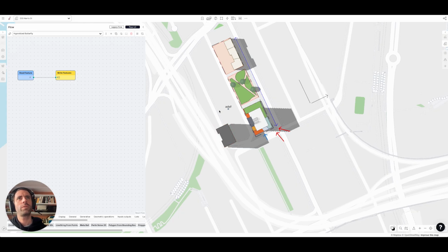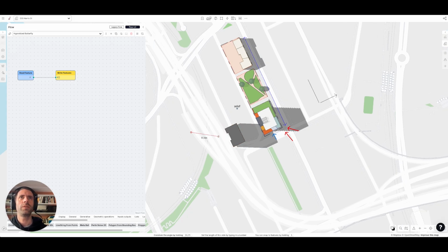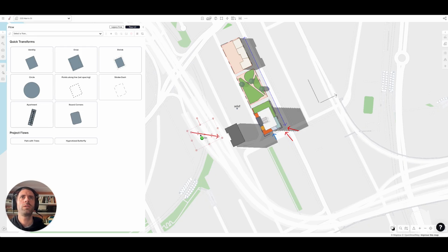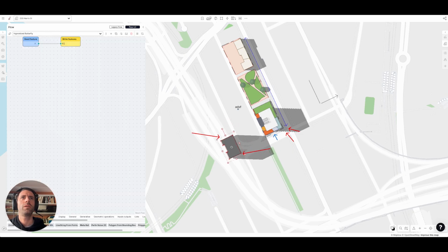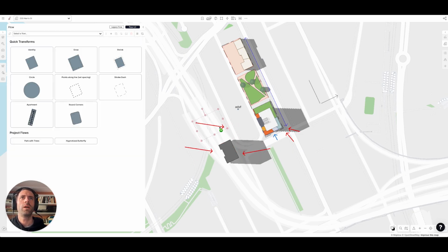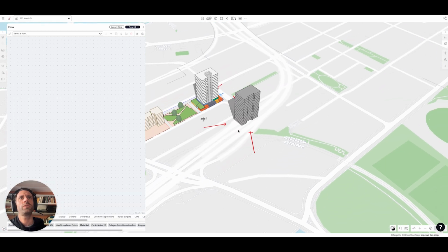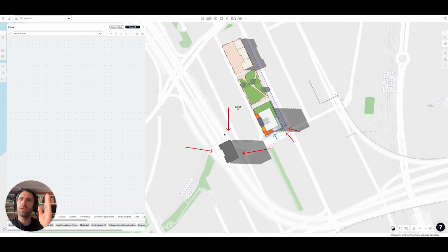I want the western sun, which comes from the west and is low down, hitting into our building. Normally you put vertical louvers, because with horizontal louvers the sun's so low it comes in between. Same with the eastern sun, although western sun in Sydney is terrible. Northern sun is different because the sun's very high. So this facade wants to be adaptive. If something's more northy than westy, it should be horizontal. If it's westy and easty, it should be vertical. And if it's south, it should be nothing because there's very limited sun in the south.